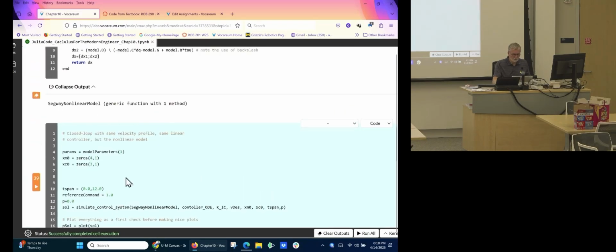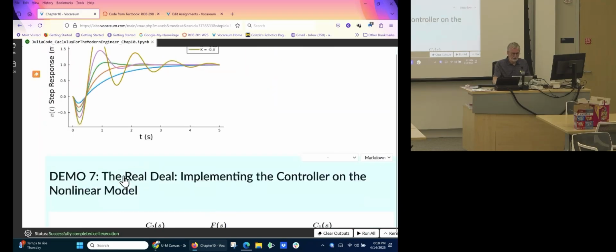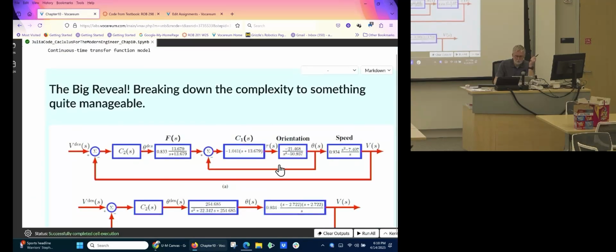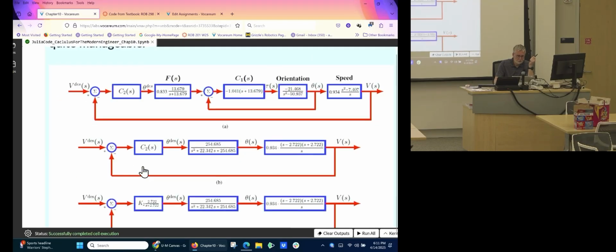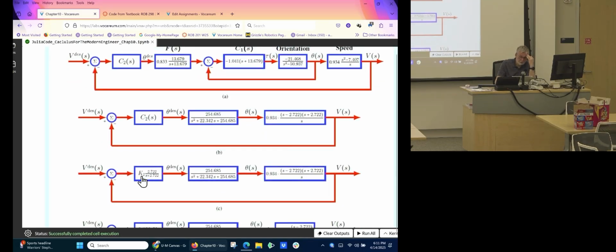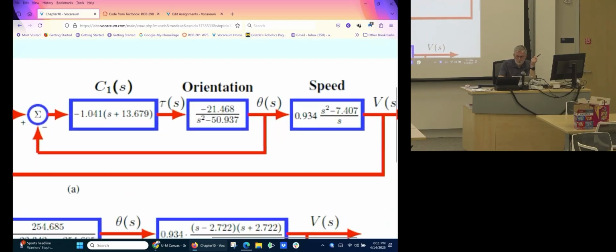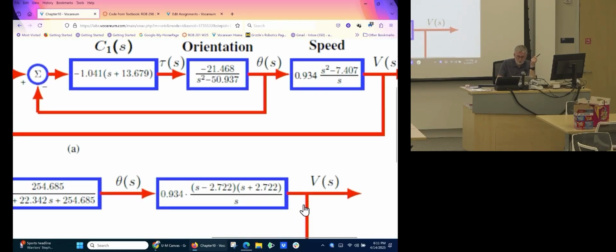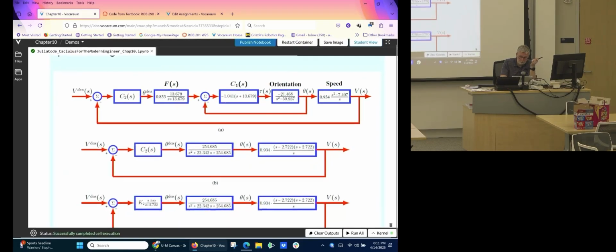Okay, so the first part, I think you'll have no trouble with the PD controller and the feed forward. This part, it's structured. So if you go back and look at this, you're given what the compensator for the speed is going to be, but you have to factor this second part of the transfer function for the velocity. And so this and this are the same. And you can leave it in, it's just that your response is much worse.